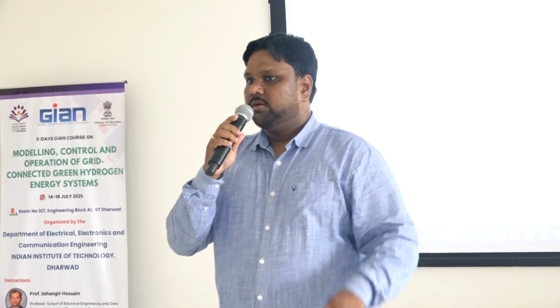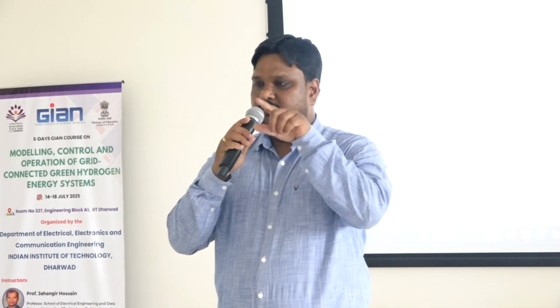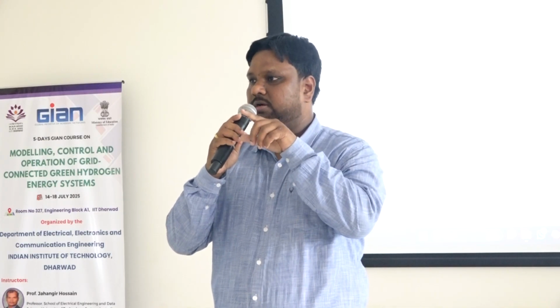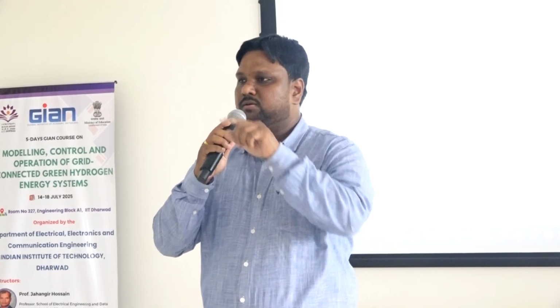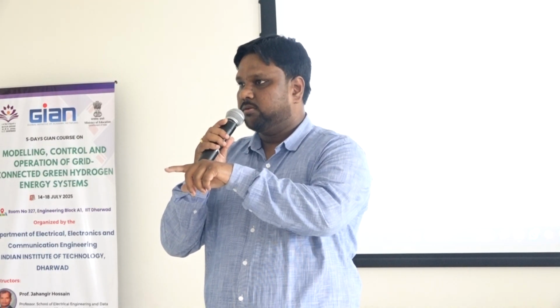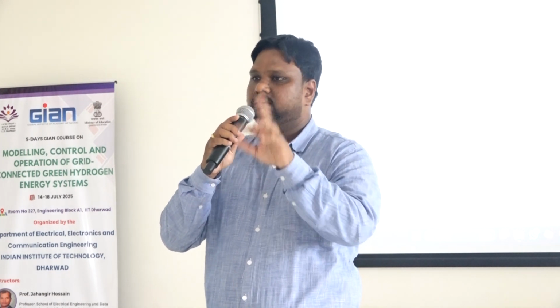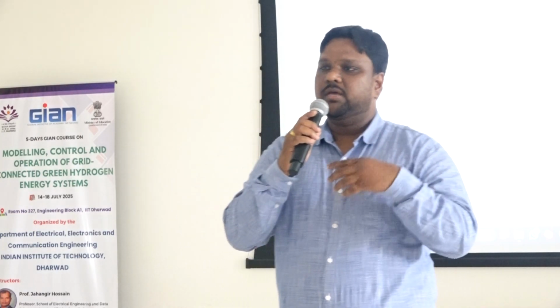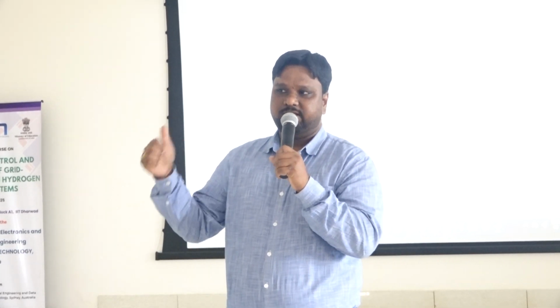If some of you remember, yesterday I gave you a power transfer equation for a DAB, with an expression something into phi into 1 minus phi. That phi is the phase shift which we are going to control. If you can control phi, you can control the power transfer. If you can control phi, you can control the output voltage. Or sometimes you have dual control: you control phi, and you control both voltage and current. So depending upon each objective, the end goal is to control the phase shift, and through that phase shift we generate the pulses.